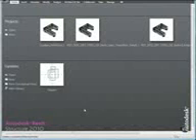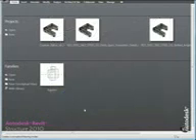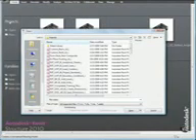In this lesson, you will create a custom beam type by changing the dimensions of the openings in a standard castellated beam. Click the menu browser and select Open. And in the Open dialog, from the Training Files Imperial folder, open the file Custom Beam.